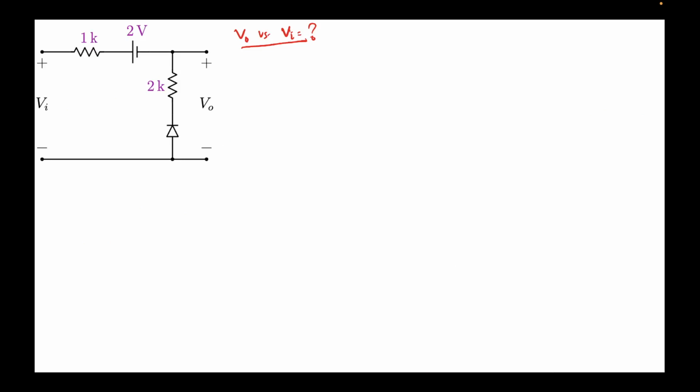So again, the same problem, rather the same approach. This will be our model again, where V on is 0.7 volts, and let's do case 1, when Vd is greater than V on. Now you can see the polarity in this question is reversed.